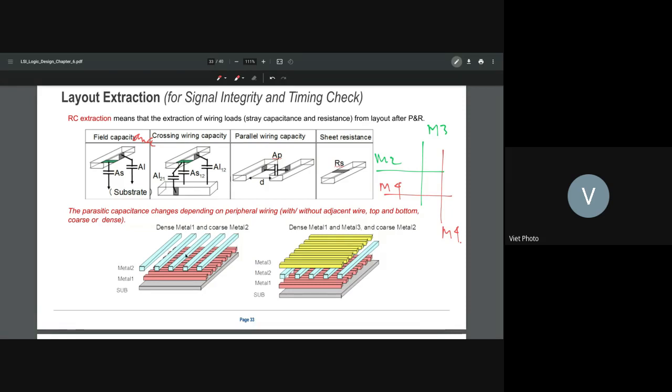Coupling. The other one is the capacitance to the ground, and the ground here is not really the substrate all the way down here. It would be the next layer because you see metal 2 here, but if we talk about a metal 10, metal 11, and metal 9, then it's far away from the substrate. So the capacitance from metal 10 to substrate is 0.